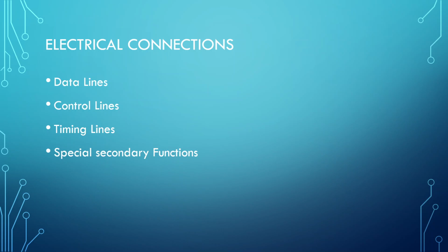So control lines are used for interactive device control, which is commonly known as hardware handshaking. And this regulates the way that data flows across the interface. Normally, if you guys have something to say, you might raise your hand, and I'll say, yes, go ahead. And you'll say your piece, and then we'll move on. That's the same idea going on here with the serial control lines. They're allowing the devices to say, hey, I have something to say, and the other to go, all right, go ahead and send it, I'm ready to listen. Instead of always having to be ready to listen.